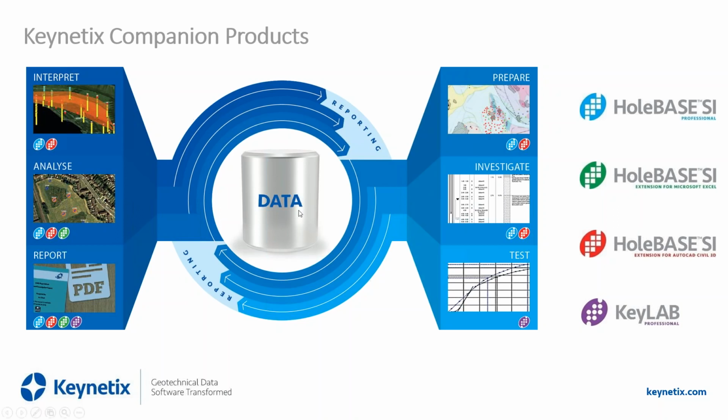So for instance, if you're working with managing geotechnical data, if you've got a whole archive of it, let's store it and make use of it. So perhaps you've been asked to tender for a new job, or you're doing a desk study, feasibility study of a new job. If you've got borings in that area, if you've already got data in that area, you can go in there and use that data. So when you're planning where to put new boreholes, how to go about doing the job, you're building upon existing knowledge, not starting from scratch. So that's how you can use data.